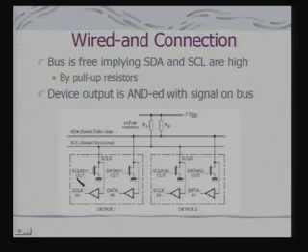What does that mean? That means that when this device intends to drive the bus, the clock should be generated by this device, else it will get the clock in, that is a clock which is currently on this line being generated by some other device. A similar thing is true for the data line, that is the SDA line as well.